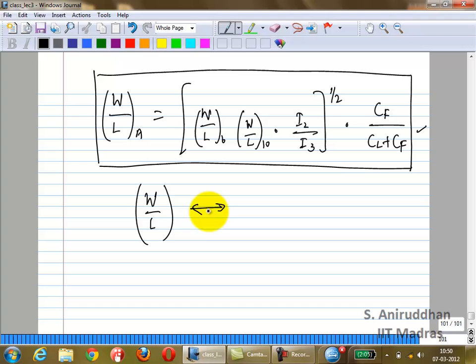Of course. Well, definitely, if you are designing an op-amp, you better know what your expected load is, right? You can also design for a maximum load. Obviously, as the load changes, your phase margin might change. Okay, that is fine. As long as in the worst condition you have good phase margin, you are happy. Just like the case where when we started off looking at it, the unity gain case was the worst case, right? You design for that, you definitely have good operation in other regions. That is the idea. Okay? Is that clear? Any questions?